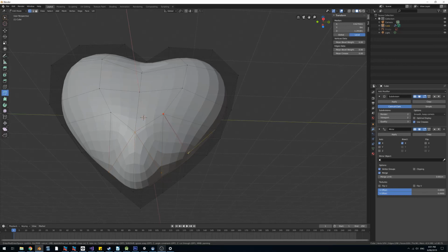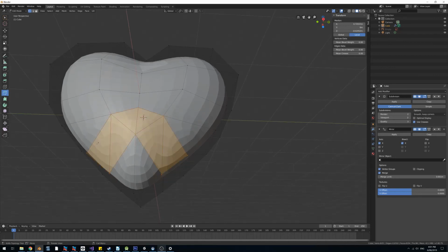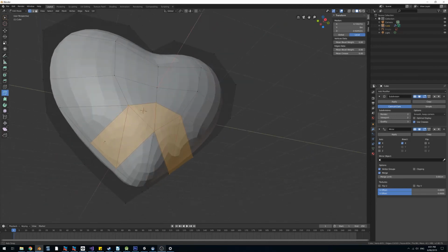So what I've done here is I've selected the mesh where it was terminating, and I've cut up to this point where all the edges come together. And then I'm going to cut across to the middle, follow it down to the same part on the other side, and then connect up the mesh where it was terminating before. And I'm going to choose accept. So hopefully that was something you could follow.